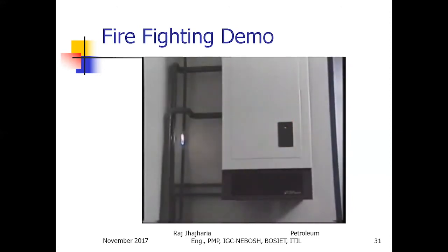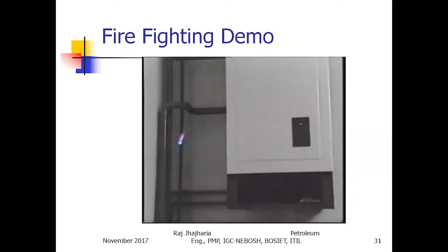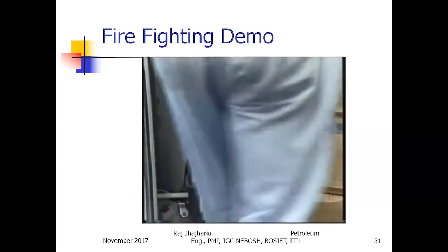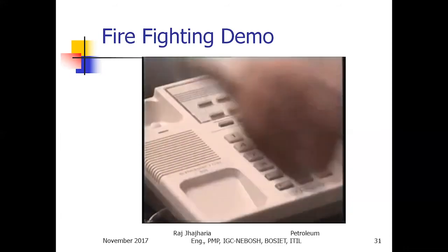Under no circumstances should you attempt to fight a fire that involves burning gases. The only action to be taken in these circumstances, and only if it's safe to do so, is to turn off the gas supply and call the fire brigade.